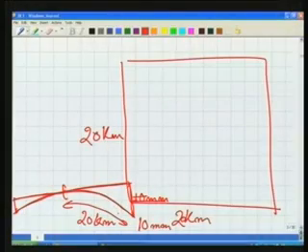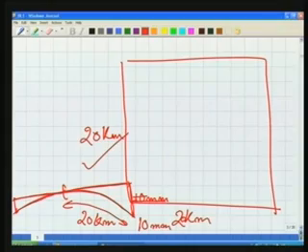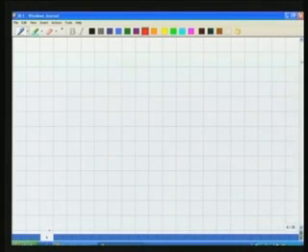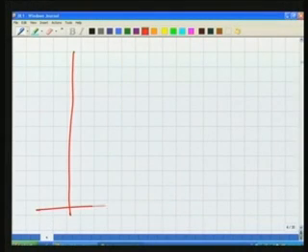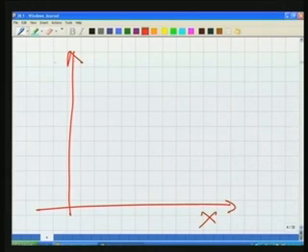Why should we measure along the curvature? We can rather measure the distance on the ground by making a line which is horizontal, and we measure this distance along the horizontal. What we are doing is we are not considering the curvature of the earth. Rather, the other way, we are considering our earth to be flat. So for small areas like this, we can consider our earth to be flat and we can easily carry out the surveying. So flat means in that case our reference plane for x and y will be like this, x and y, while the z are being measured from the geoid.